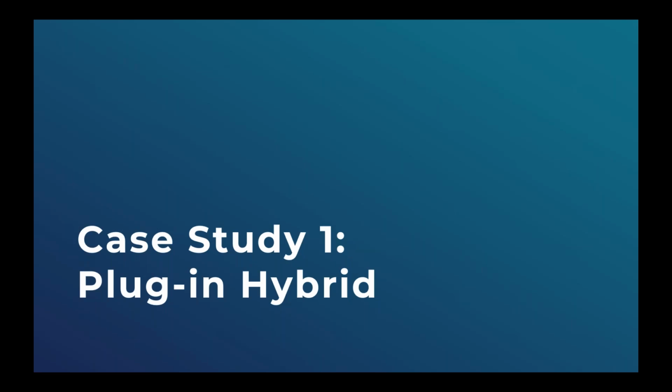So our first case study is the plug-in hybrid vehicle. So we have a 4-volt nominal cell. This is a prismatic cell, so the electrodes are wound in a jelly roll and then kind of smushed down and stuck in a can. And this is common in a lot of hybrid electric vehicles.